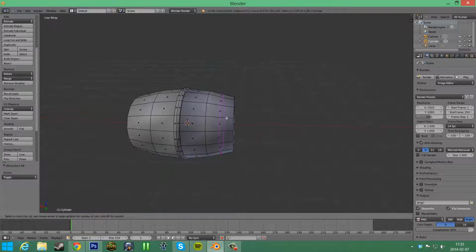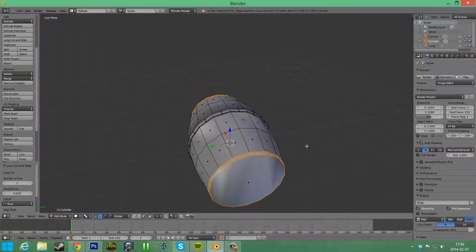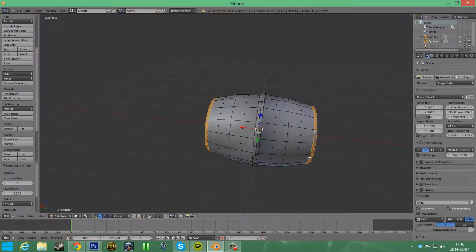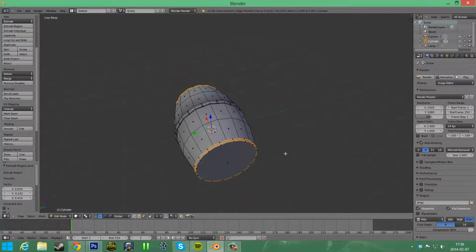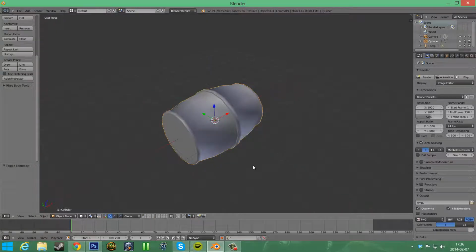So let's just press Control R, move a little edge there. Let's do 0.8. We could do that. 0.8. And then same here, but now it's negative 0.8. And then we can take them both at the same time, so we know it's correct or exactly symmetrical. So S, Shift X. Oh no, actually E first. So we get the extrude, and then S, Shift X. Let's scale it up a bit, like that.